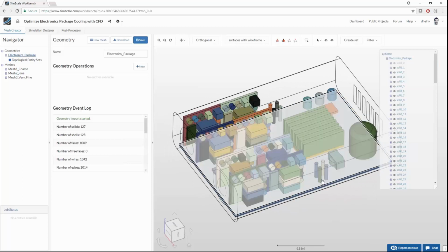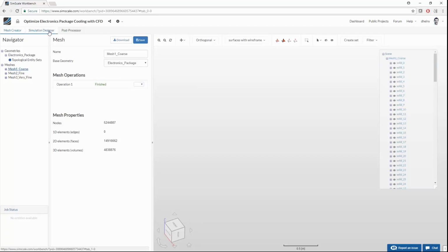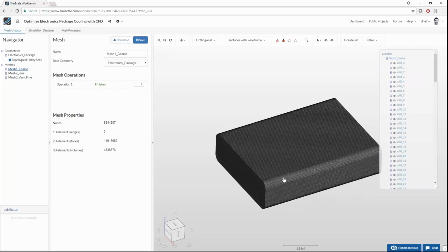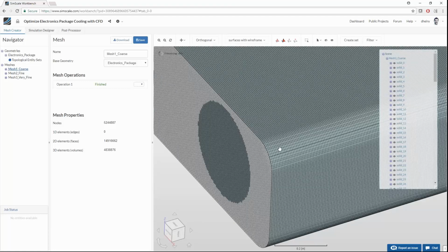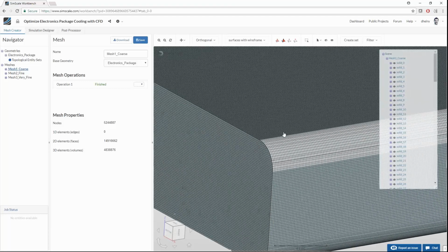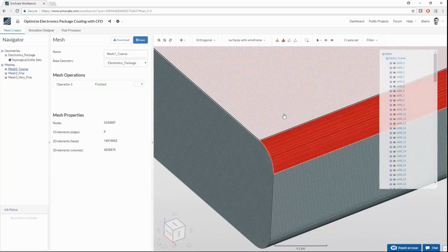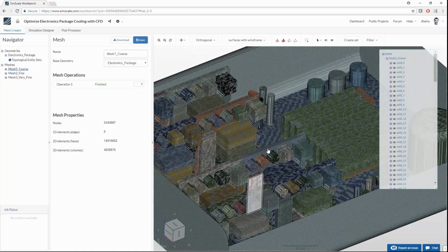And for you to get a feeling for the next workflow step, you typically start by generating a computational mesh for it. Depending on if you're looking at a finite volume or a finite element solver, you have different mesh generation methods available. And how this looks is, now we're loading there, without going into the details, zooming in, you can see that the CAD model has been discretized into many small cells that are going to be used in the simulation, right? You can see here also the inner components, etc.